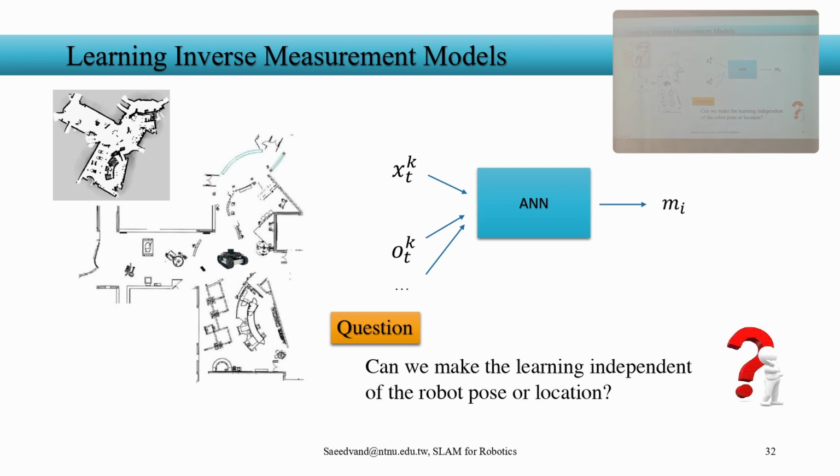This is relative. The coordinate will be relative to the robot pose dynamically, which you can consider always 0, 0 if you remove the pose. If it's 0, 0, it just says distance and angle: range and bearing always. Then those range and bearing outputs without x, you should merge them together because you have a bunch of them.